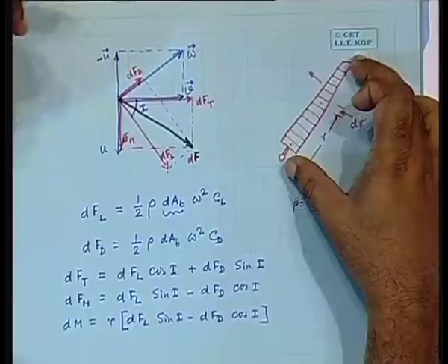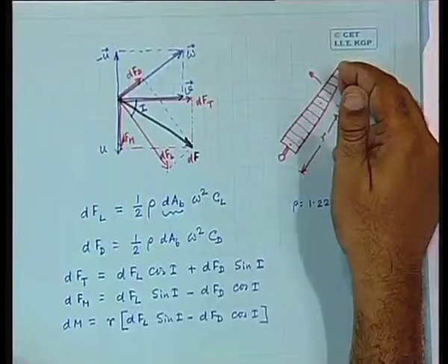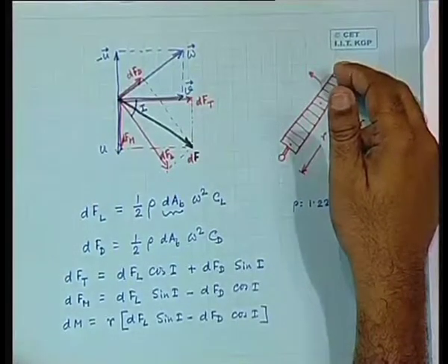There will be another force: here is the blade and there is a thrust force produced. There will be a larger thrust force toward the tip, and a smaller thrust force toward the inside of the blade. As a result, a bending force is produced, and that might also be a cause of failure. Generally, people try to avoid this problem by two means.